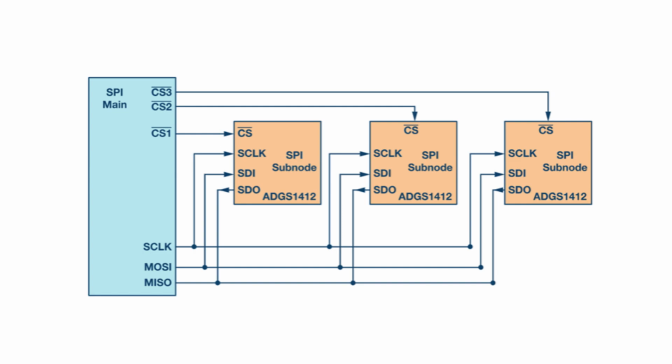What you absolutely should not do is try to somehow fake it in software or hope it just works at low speeds. Mismatched modes fundamentally break the timing protocol. Don't waste time trying to force it. Use separate peripherals if needed. Okay, clear advice there. Use separate buses.